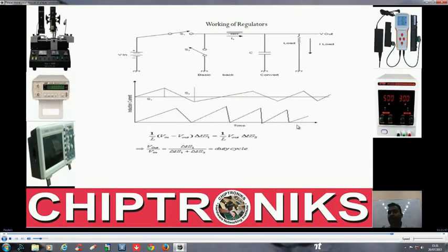So this is very fundamental which I am speaking. There is always a source and a sink. The source in the notebook motherboard is the DC jack, whereas the sink is the processor. The processor requires the least voltage, but it requires the highest current, whereas at the DC jack, we have the highest voltages and the least current. And the job of a regulator is to generate the various voltages from one fixed voltage as required by the electronic device.